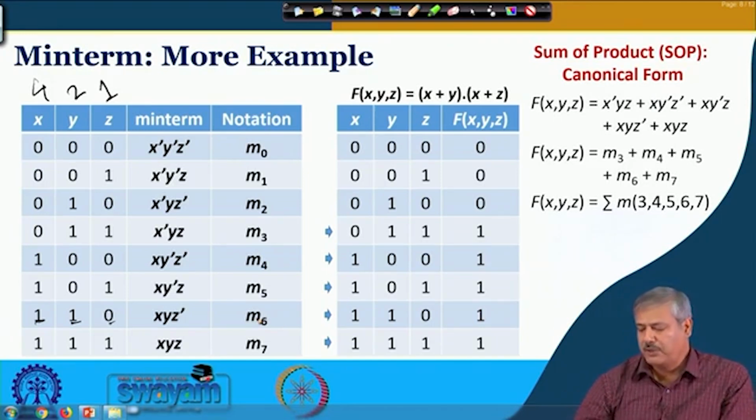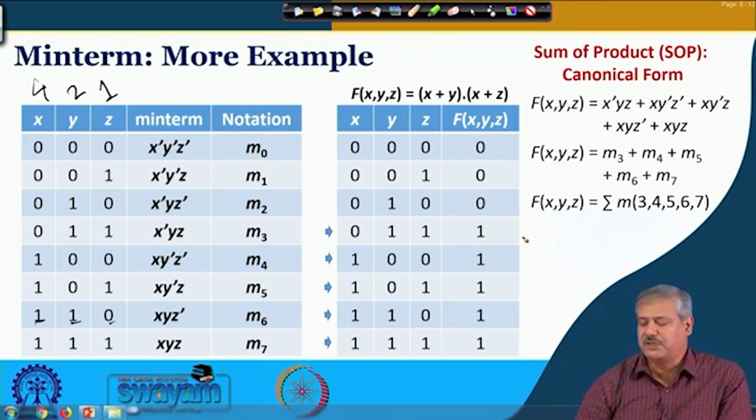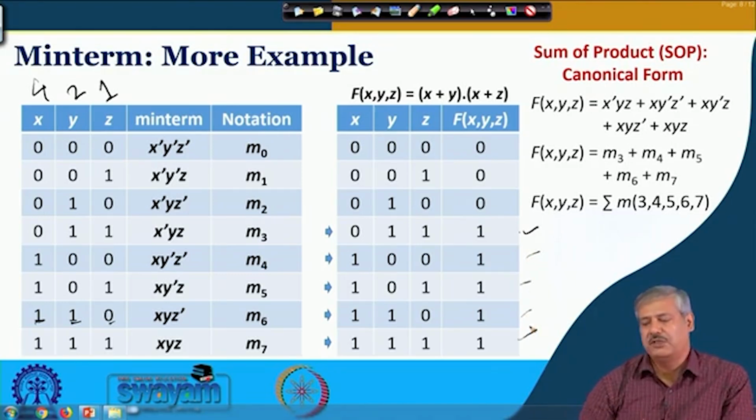Okay. And if we look at this particular truth table, this truth table we have seen before, but here we are just looking at, given a truth table, how we are converting it to a corresponding Boolean expression. Here we are talking about expression that has min terms. So, we shall look at the terms that are having all ones. So, these are the terms that are having ones: 1, 2, 3, 4, 5. So, 5 min terms will be there and which will be summed to get the corresponding Boolean expression, right.